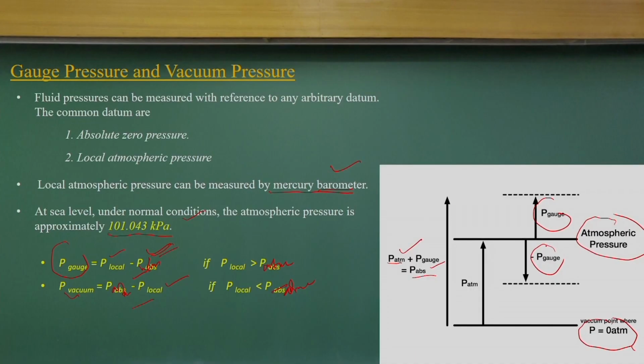Like many of the problems you solve, the fluid has a boundary at the atmospheric pressure level. At that time we can measure the pressure difference: the positive side we call the gauge pressure, and the negative side we call vacuum or suction pressure, which is below the atmospheric pressure. We never go below the absolute pressure of 0 atmosphere, or no pressure, which is the vacuum level.